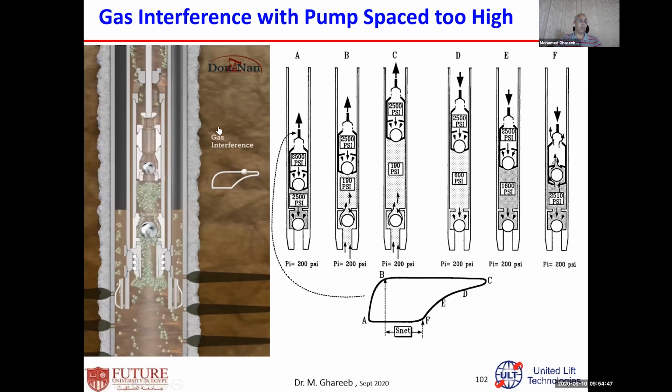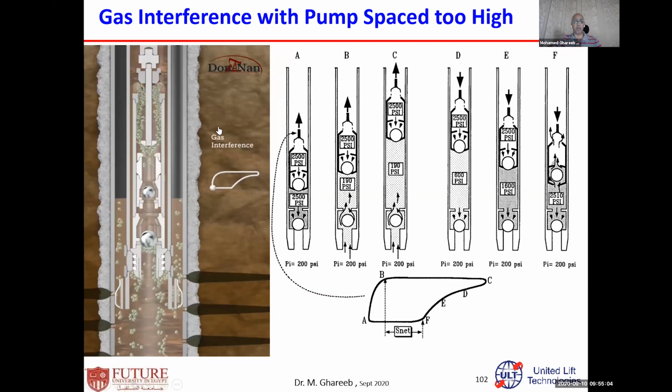In the worst case, under some conditions, can this pump reach what we call gas lock? There is a difference between gas interference and gas lock. When the valve is open at a certain position and the other is closed, open and closed, and there is a displacement, there is a production, that is what we call gas interference. What happens if I have a very high volume of gas here and I design or operate my pump badly? I will show you later how some pump design and operation problems can create more problems in case of gas, what we call gas lock.